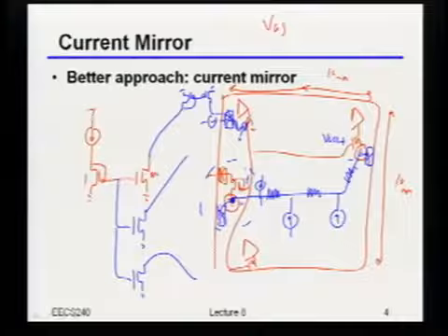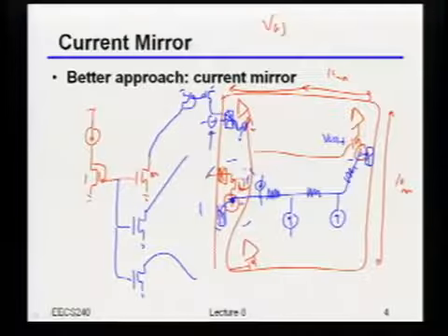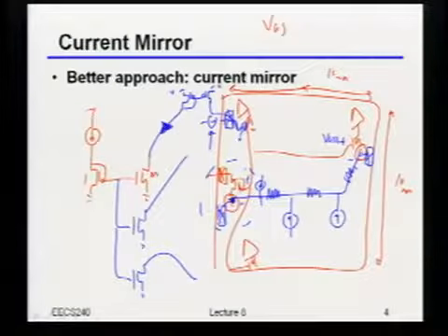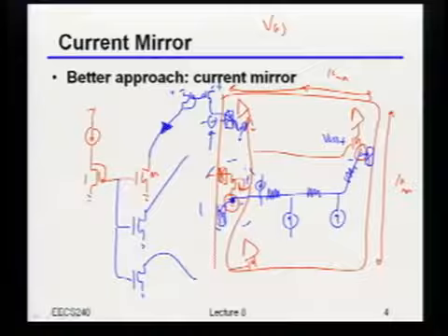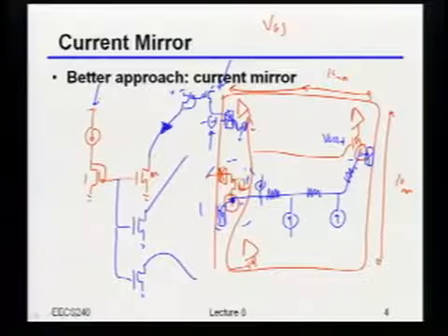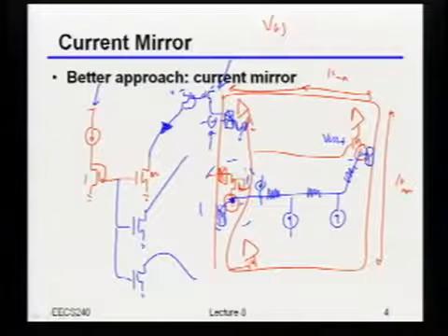So now I'm creating this quote-unquote external current, but I'm doing it on the die. The reason this is good is because current's current. If there's some number of microamps, there's some number of microamps. So no matter what the supply drop is, or what the difference in VDD at this point versus VDD at that point is, it doesn't matter, because I'm just going to re-reference myself to that local point.